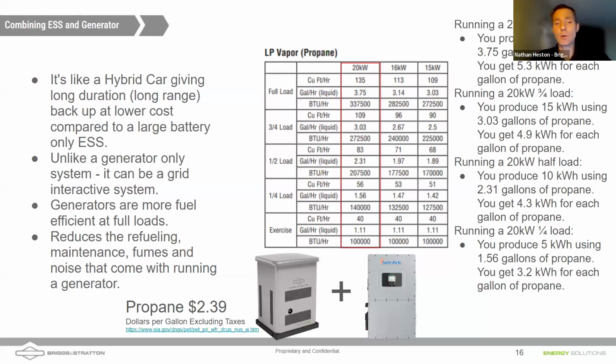Absolutely. You can have DC solar and a generator running to charge your batteries at the same time. When you are doing AC coupled solar, you don't want both of those devices running at the same time, because you don't want that generator getting backfed from the microinverters or the AC coupled solar. We're going to address a way that you can block them out. But typically, if your solar is producing, your loads should be covered from that solar. There would be rare instances, such as very early in the morning and in the evening when the solar is weak, with AC coupled solar, where you would have to shut off the solar in order to run the generator.